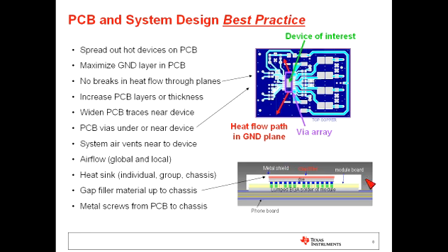And we have the metal shield over the device, and the recommendation which was implemented was to take a gap filler material, and this could be a grease, this could be an epoxy material, this could be a compressible thermal pad that connects from the component to this metal shield, giving a much, much lower thermal resistance than that air gap. Air gaps tend to have a very poor thermal resistance. And now there's a pretty reasonable thermal path from the device up into this metal shield. And this metal shield, which was already there, or this could be the chassis for the enclosure, which was already there for mechanical reasons or for electrical reasons, is now providing a significant thermal benefit at very little added cost or complexity. You can read through some of these other examples.